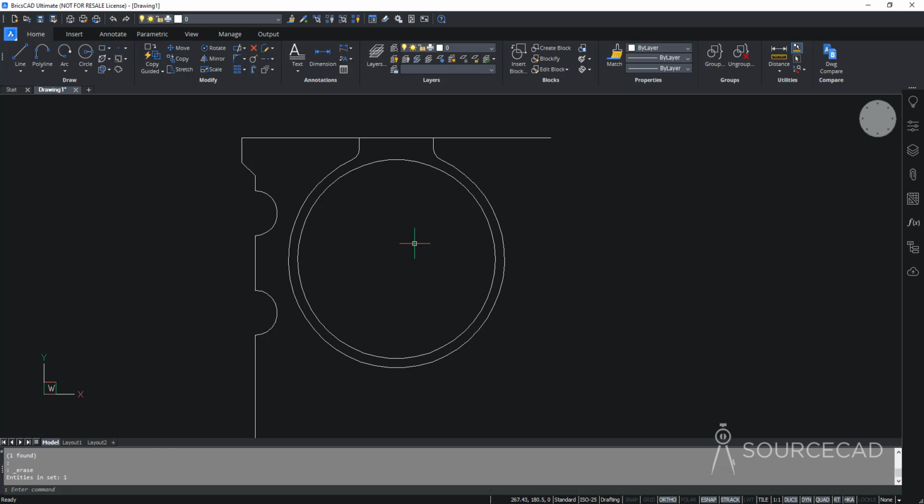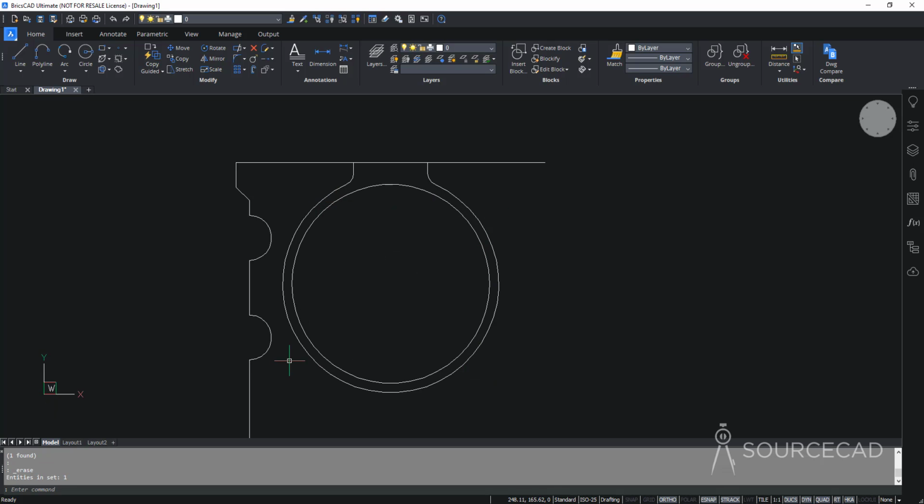And we now need 4 circles here. So let's start with again a construction line. And using this center as a reference, I'll make a construction line at an angle of 45 degrees. Now, as you can see, it's just making it horizontally or vertically. So I'll deactivate ortho and activate polar once again. Now the angle is 45.